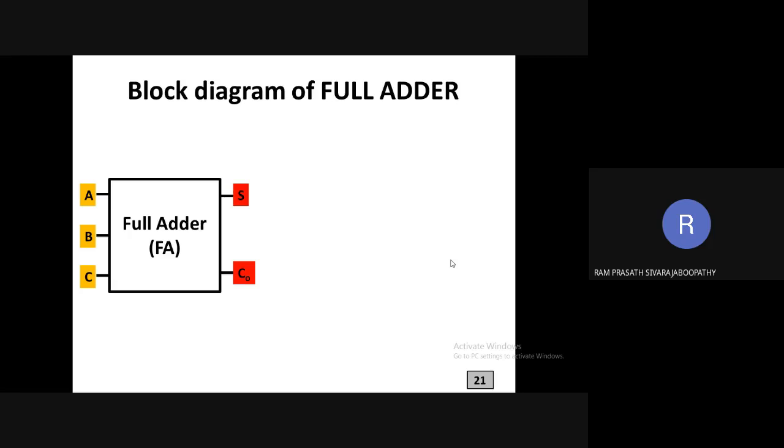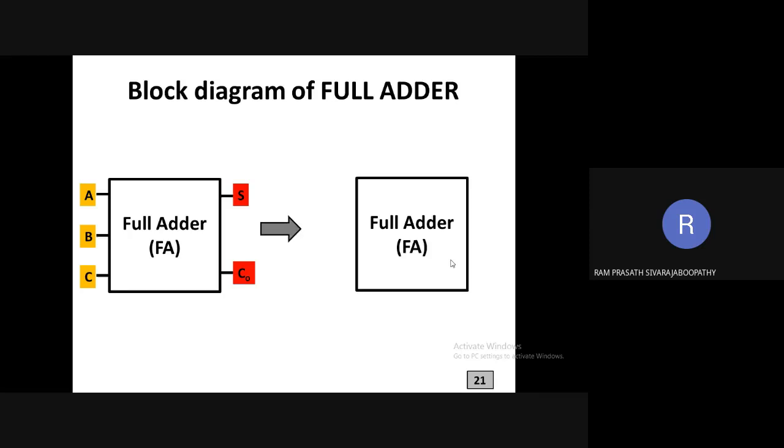For implementing this circuit, we are just going to rearrange the inputs and outputs in some manner. So we are having the full adder. Inputs are marked in yellow color. So it is mentioned as AI, BI, CI. What I stands for is individual bits. A0, B0, C0, A1, B1, C1, like that we can assume. So the outputs are like this.